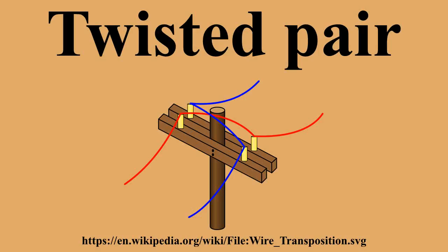Bonded twisted pair: a twisted pair variant in which the pairs are individually bonded to increase robustness of the cable. Pioneered by Belden, it means the electrical specifications of the cable are maintained despite rough handling. Twisted ribboned cable: a variant of standard ribbon cable in which adjacent pairs of conductors are bonded and twisted together. The twisted pairs are then lightly bonded to each other in a ribbon format. Periodically along the ribbon there are short sections with no twisting to enable connectors and PCB headers to be terminated using the usual ribbon cable IDC techniques.